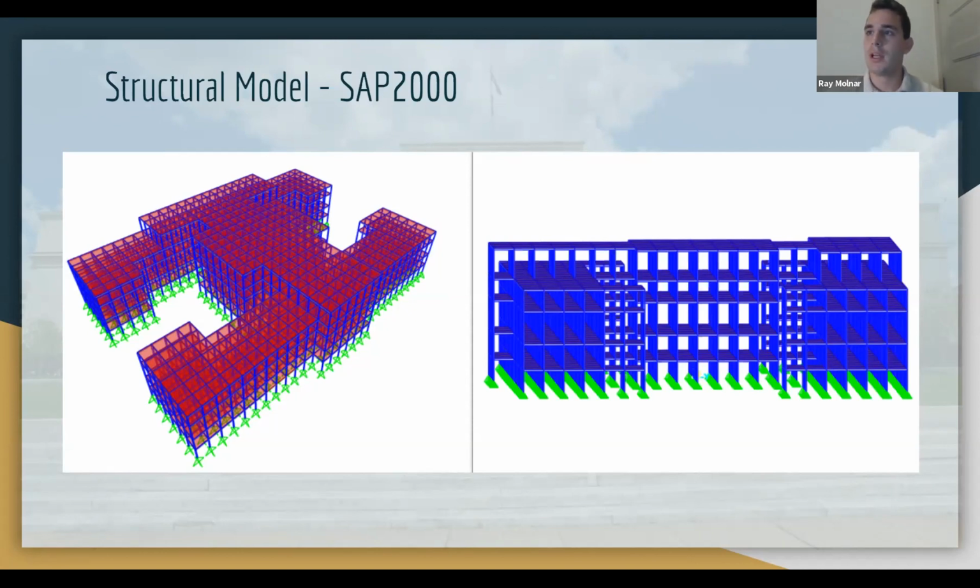So to design the green roof terrace for the Federal Reserve building, we had to obviously calculate the load capacity of the existing structure in order to figure out what additional loads could be applied to the rooftop without exceeding the capacity of the building's structural elements. With a building of this magnitude, the model seen above has to be broken up into simple frame sections. This allows us to size and design the building elements according to the loads acting on the 2D frames.